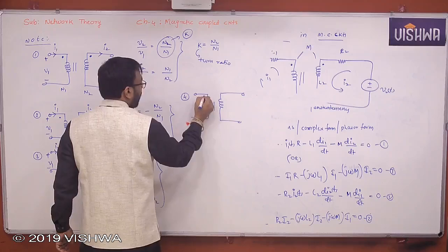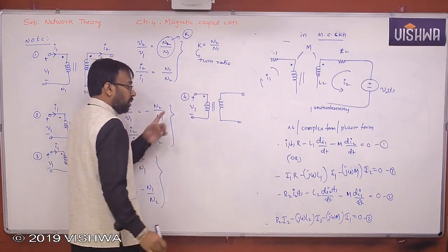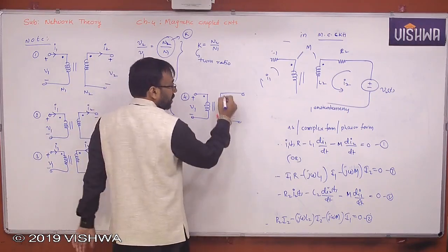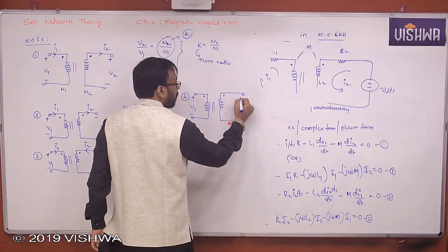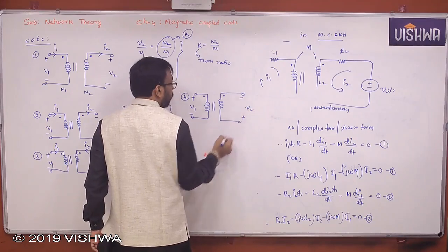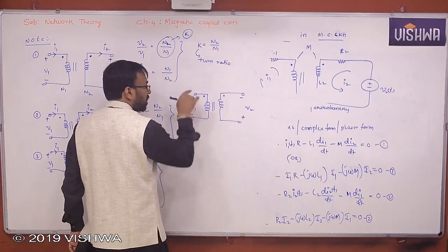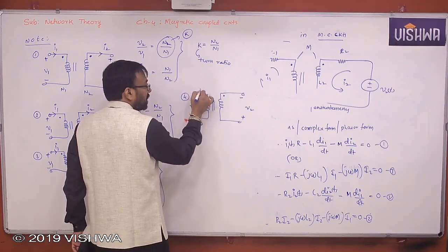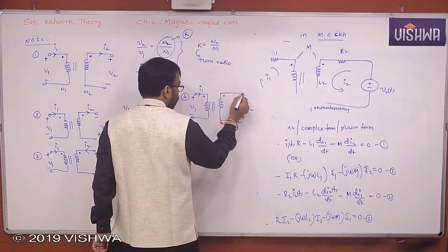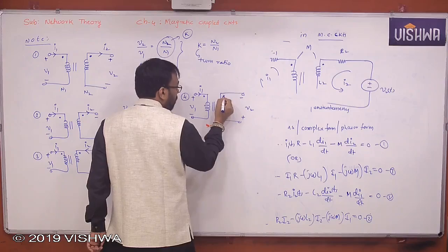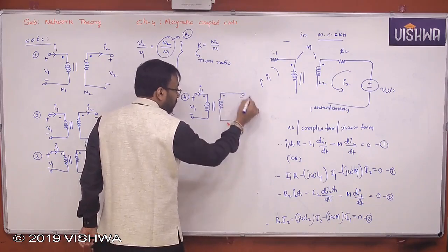This is the actual polarity, plus minus, but how is he measuring using the voltmeter with the same polarities? This is supposed to be plus minus, but how are you measuring the voltage? Say minus plus V2. The ammeter is supposed to be connected plus minus because current flows from higher potential to lower potential. This is the direction, that means I1. The ammeter is supposed to be placed to measure the positive current because this is higher potential and this is a lower potential. When you connect a load across it, higher to lower, the current flows this way.